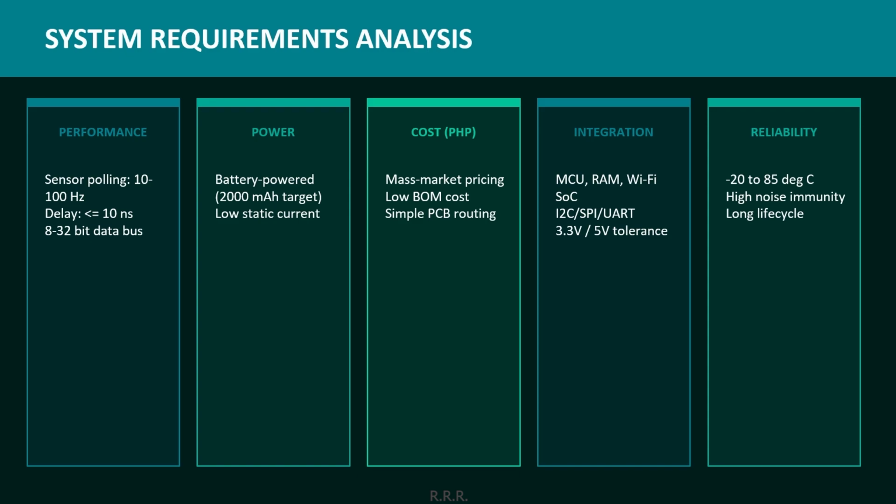Second, power consumption. This device is battery-powered. We are targeting a 2000 mAh lithium-ion cell. Low power consumption is not just a nice-to-have, it is a product requirement. A logic family that drains the battery in 10 hours simply will not make it to market.